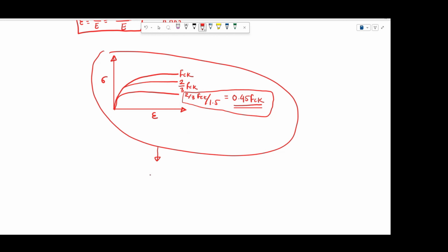Whenever you see the Whitney stress block, in that stress block this is your tensile force, which comes out to be 0.87 Fy into Ast, on the bottom portion. This is just a concentrated force acting at the level where exactly your bars are.